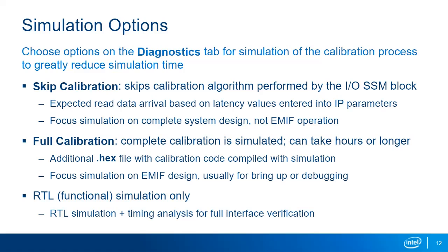Gate-level simulation of the EMIF IP is not supported. It is recommended instead to perform an RTL simulation for functional verification and use timing analysis, discussed later, to verify that the interface meets gate-level timing requirements.